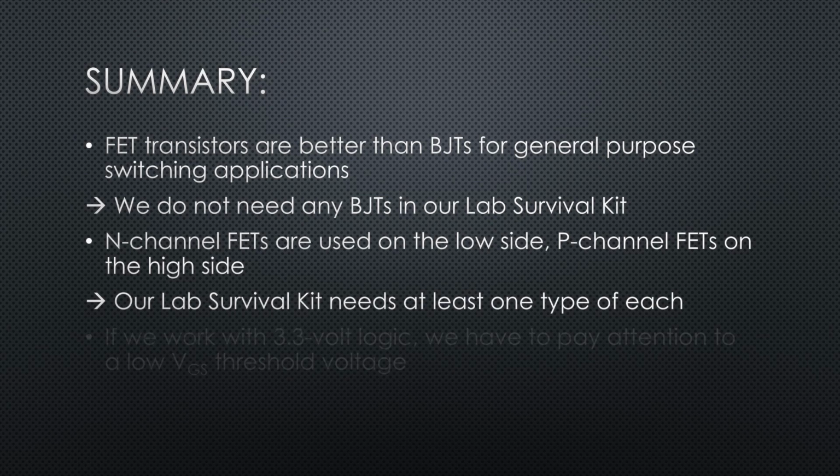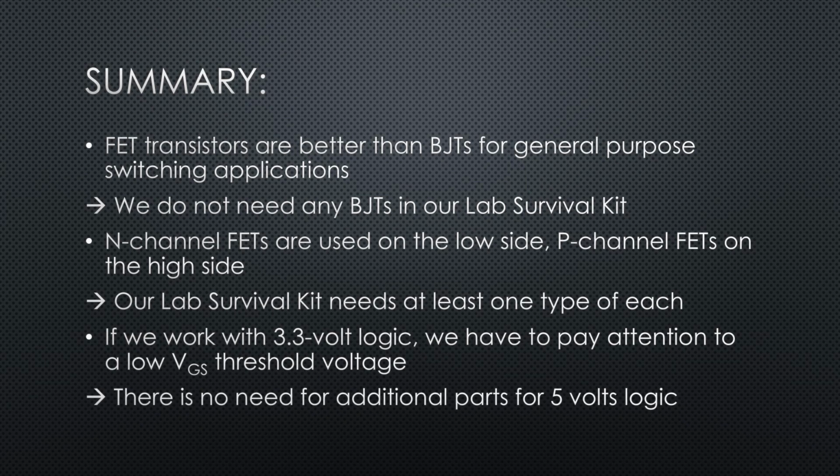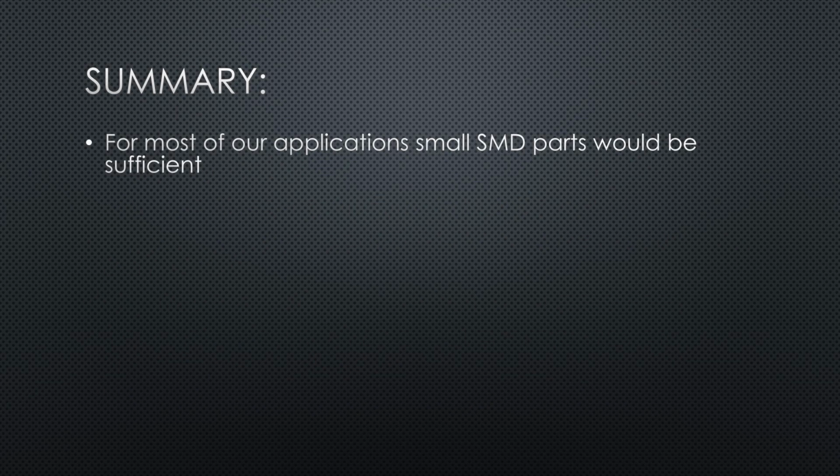Especially if we work with 3.3 volt logic, we have to pay attention that we get them with a low VGS threshold voltage. Otherwise, they will not switch on. Because these types also safely work on 5-volt logic, there is no need for an additional type. As we saw before, for most of our applications, small SMD parts would be sufficient.